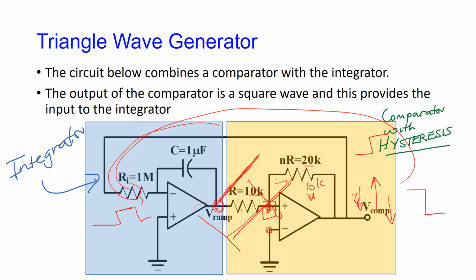But just in concept, if I had a comparator, and I put like 5 volts here, then as soon as the ramp goes more than 5 volts, this will toggle. And then when it's coming back, when it goes less than 5 volts, it will toggle again. Are we setting that particular voltage by how we choose those 2 resistors? Think of it that way.